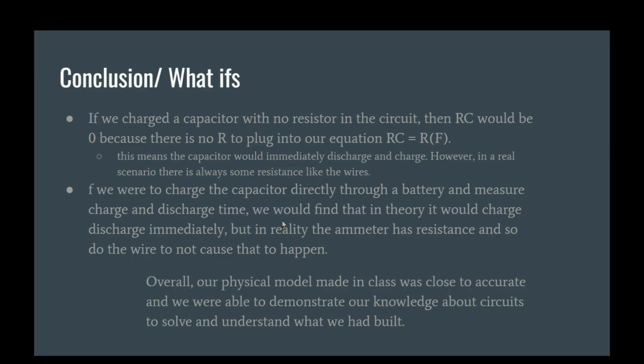Some what ifs: if we had charged a capacitor with no resistor in the circuit, the RC would be 0 because there is no resistance to plug into our equation. Again, 0 times any number will be 0. So if we have no resistor, the capacitor would immediately charge and discharge. But in a real scenario, there's always some resistance, like wires.